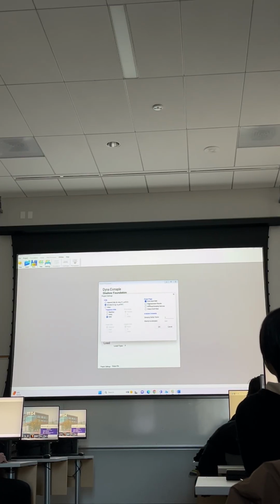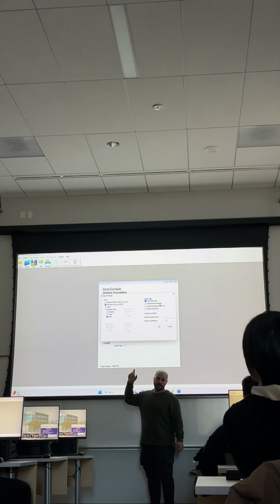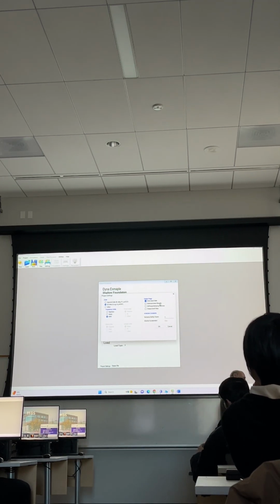Okay. For the output flags, there is the equal input option, we need this. There is a dimensionless result option. This will normalize the result and normalize the response. So please don't check this one. You don't need to check this one. Okay? We will need to get the response in meters or millimeters or something like that. So we don't need the dimensionless result.